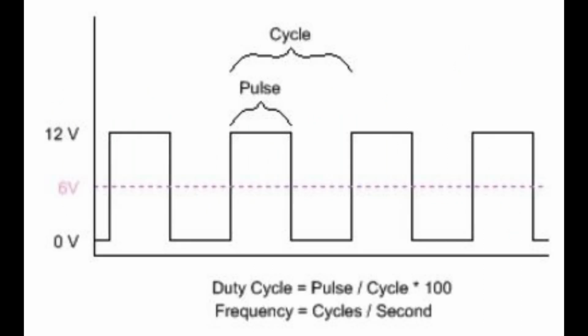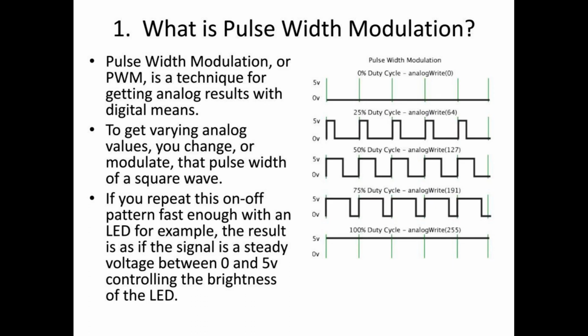So let us understand what is pulse width modulation. This is a modulation technique which creates pulses of variable width to represent the amplitude of an analog input signal while keeping the frequency constant. This is done by timing on-off signals so that this PWM technique can be used to adjust the power delivered to the load. This technique can be used for different things, such as to vary the intensity of light.